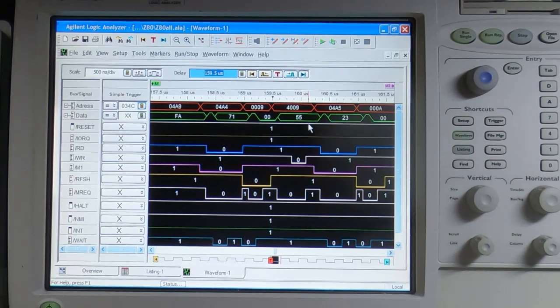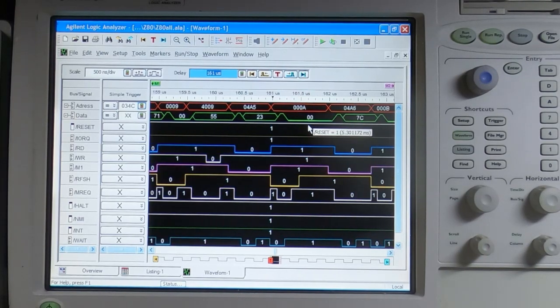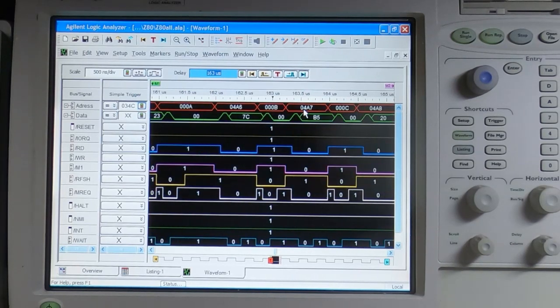So it will then obviously loop round and do the same thing again, and these addresses here, 000A, B, C, are the first few addresses in the ROM. So when it returned from the function that it had jumped to do the RAM test, it returned to 000 instead of the return address.